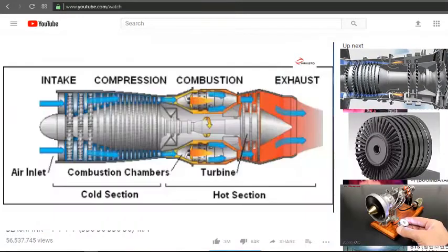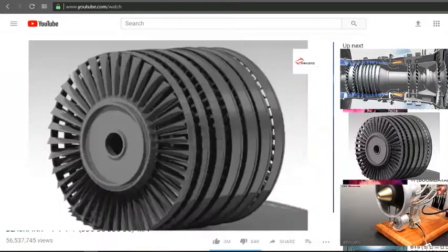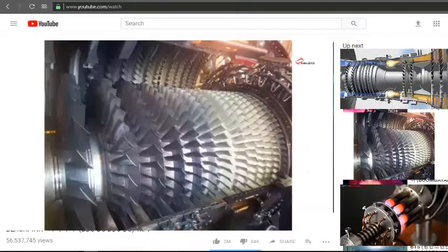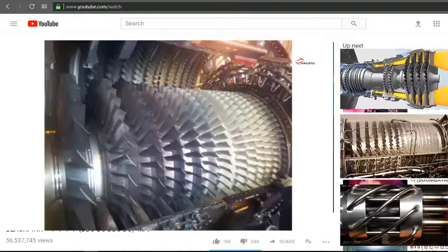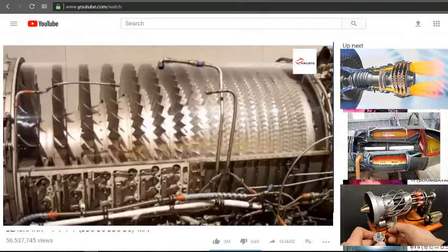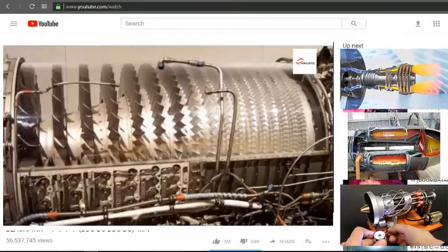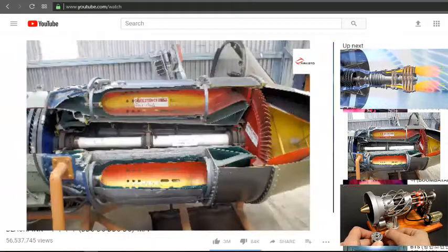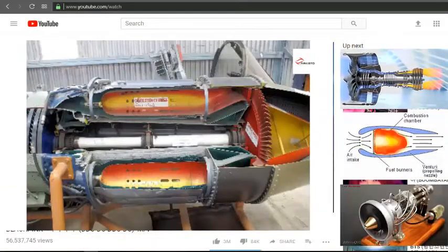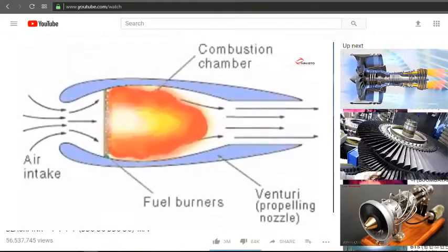Parts in jet engines. Compressor. The compressor is the first component of the engine. It has many blades and is attached to the main shaft. The compressor sucks and squeezes the air as it moves further, which results in very high pressure of air. Combustor. In this part, the compressed air is mixed with the fuel and ignited. The heat can reach up to 2700 C.